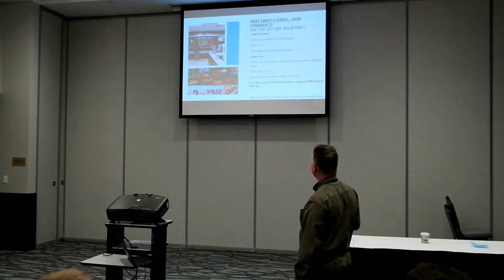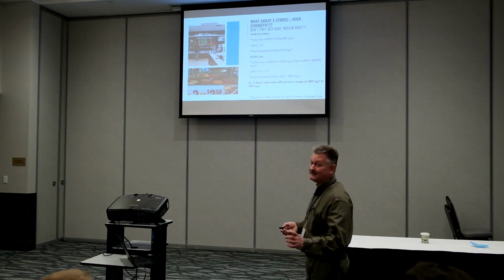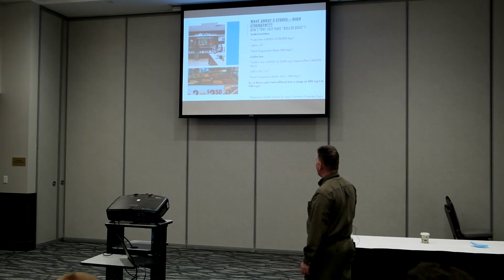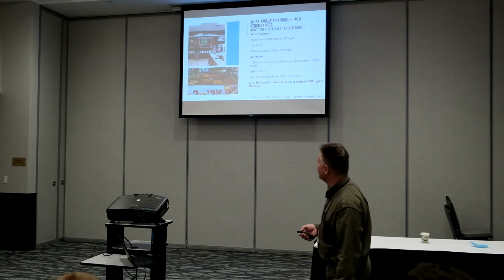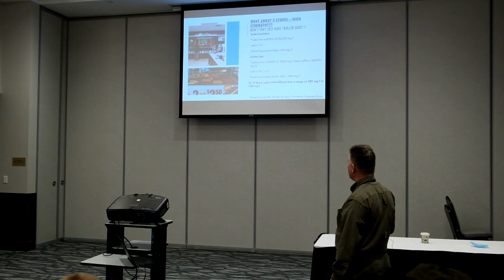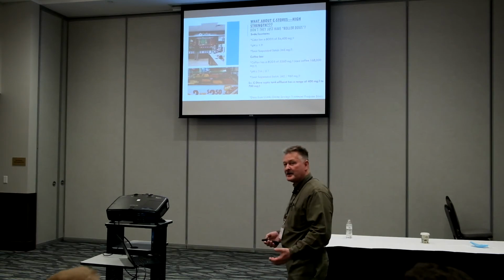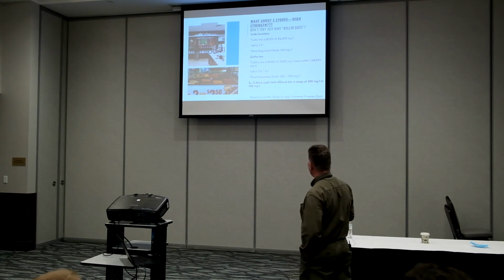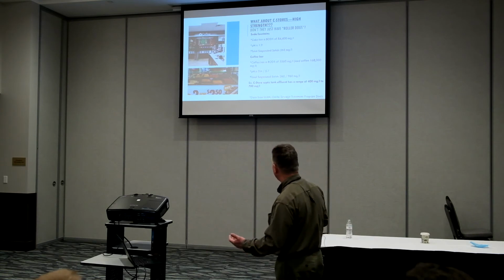Well, you look at Coke, it has a BOD of 84,000 milligrams per liter. Again, residential is 150, so a little bit of difference. It also has a very low pH. They all have coffee bars, and they're always refreshing that coffee. We all like fresh coffee. BOD from coffee is around 5,500. If you get into iced coffee, it's 168,000 milligrams per liter, because of the sugars and the creams and so forth that we're putting in there. And of course, we're getting some dilution occurring from the wastewater, the black water, and so forth.